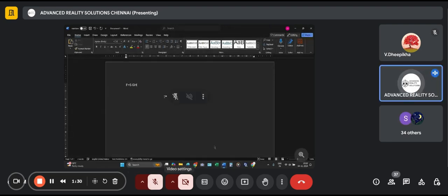Frequency is 5 gigahertz. FR4 is my material. So this is going to be my reference document. Whenever you design an antenna, you make a document like this, so you can clearly mention everything. Frequency, F is equal to 5 gigahertz, and type of substrate, FR4. According to the substrate type, we have other values.